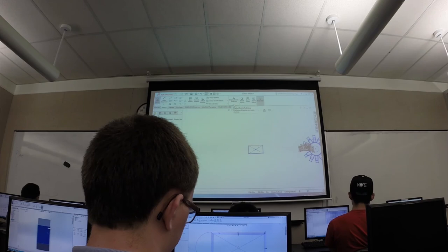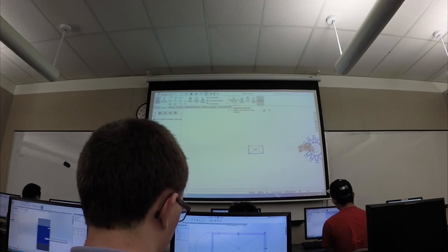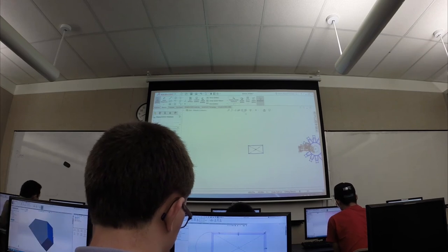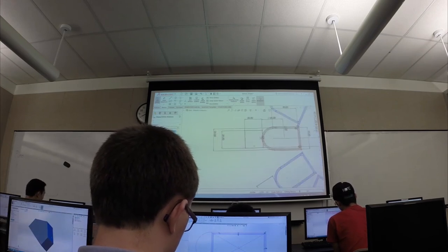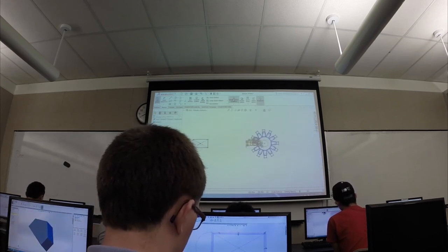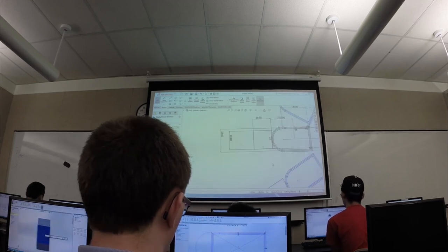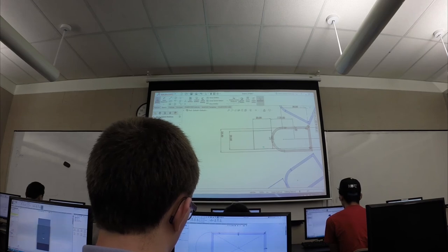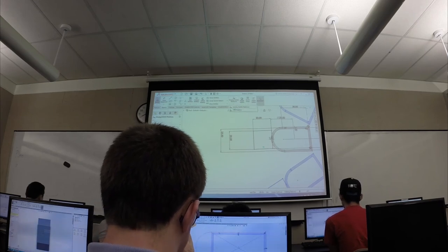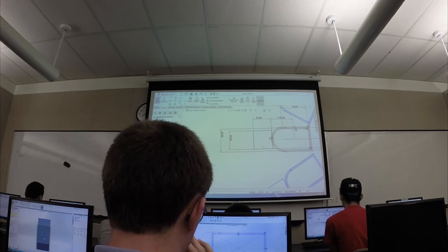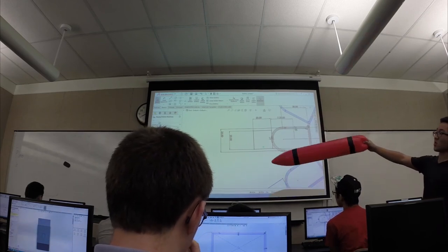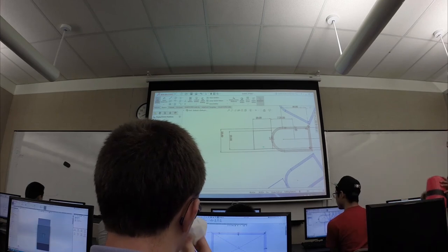Next thing we're going to talk about is this button right there, display delete relations. So when you click on that, it automatically tries to show you all the relations that there currently are. So you can see on the property managers that all the relationships in this current sketch are shown to you right now.